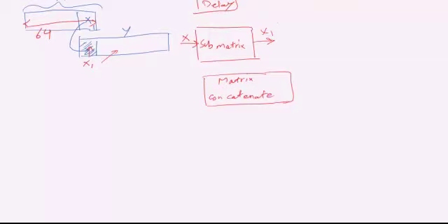The next part in the block diagram that I showed you a few minutes before was to take the FFT, and Simulink has a block called FFT, which takes the FFT of the signal. It is a 64 point FFT, so make sure you configure it for 64 points.